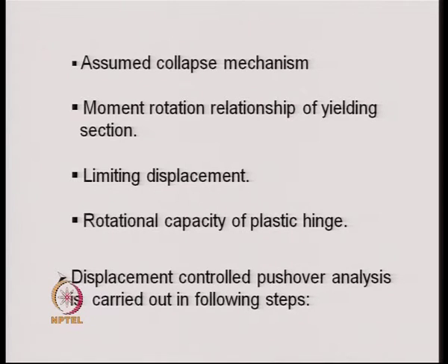Next important information that is required is the rotational capacity of the plastic hinge. That is also very important. In many cases, we say that if the rotation at a plastic hinge exceeds a certain value, then there is a rotational failure at that plastic hinge.